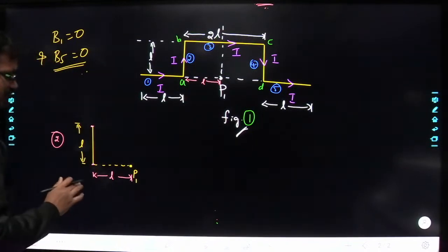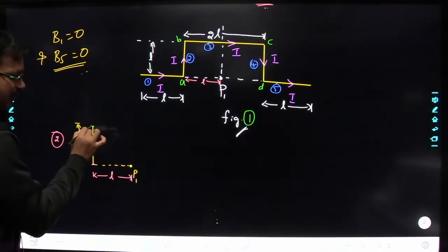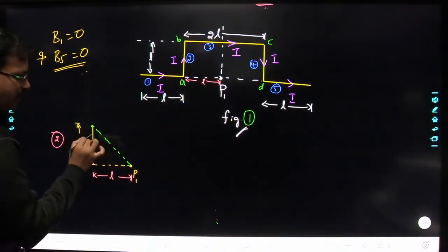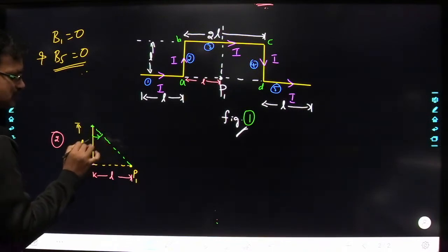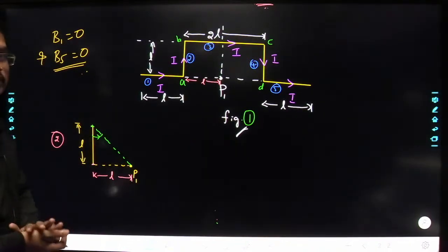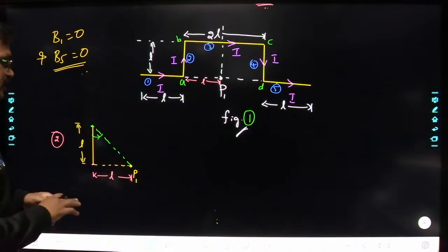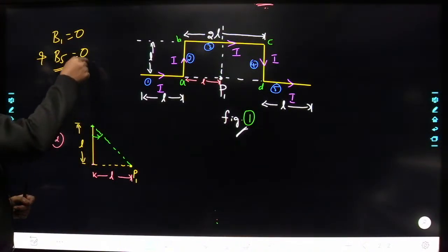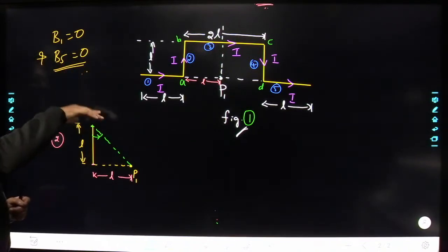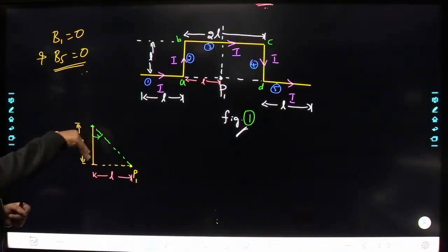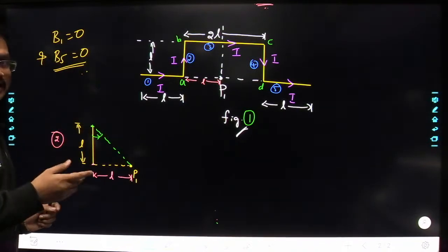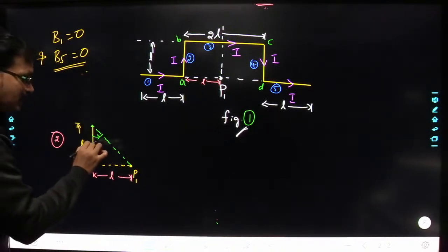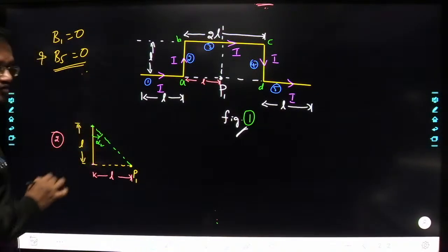Okay. Now see here. This end is making an angle. So this angle we call it as alpha 2 or alpha 1? Tell me. See how you have to determine that here. If you extend this wire up to infinity, what happens to this angle? This angle is going to decrease. So this angle we named the decreasing angle, and the decreasing angle we will consider as alpha 2.